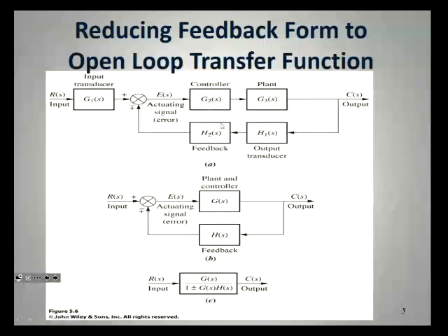So this is a fairly typical system, and of course you can combine it to make a much simpler system, like this here, just by multiplying these two to give you an equivalent here, and then you already know that the feedback is G over 1 plus GH. Told you that before. We worked that out from looking at the errors and the feedback. I think we did that last week.